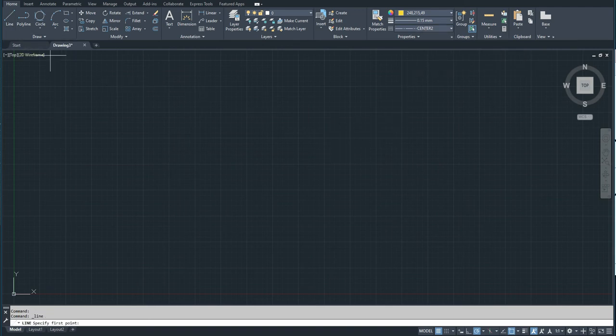I will draw a line. Say that I will draw from here to here. How can I be sure that this line is accurately in horizontal direction? We can activate the polar and be sure that it is zero angle. Click. Next step, guys, we want to draw a vertical line. So I will choose this line, and then now I'm sure using the polar it is perpendicular.